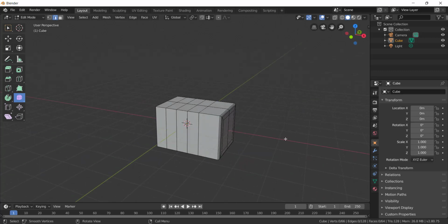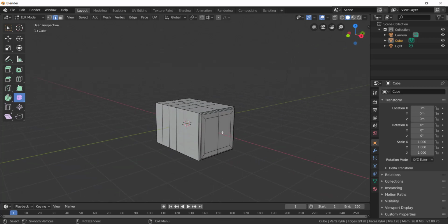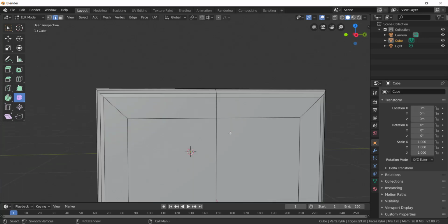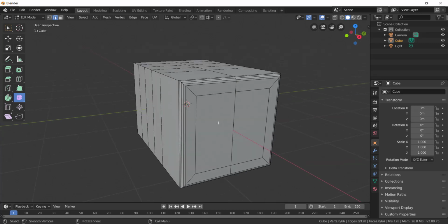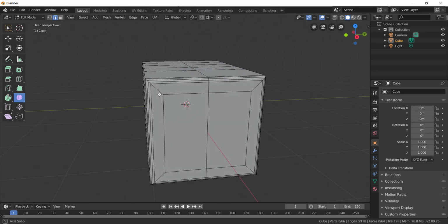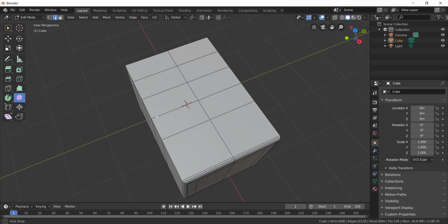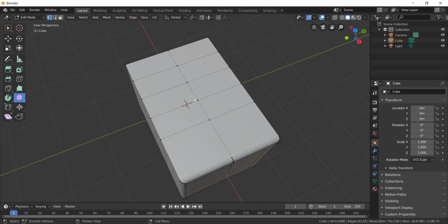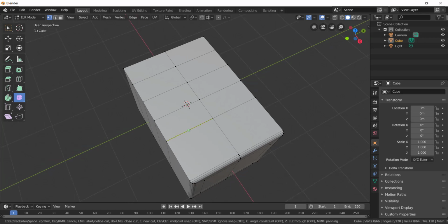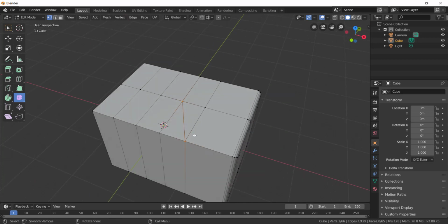And before closing the video, I want to tell you one thing about the looping. Okay, see, whatever object you are creating, you should always follow one thing, that you should never make triangles. The object should be created only with rectangles. Like, see, 1 2 3 4, it is a good loop. If there is something like this one, now this is not the correct way.